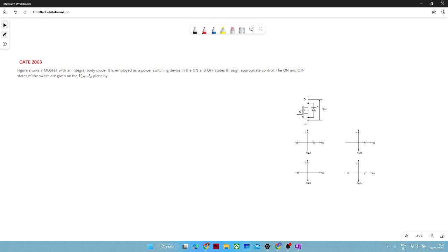It means with the help of this body diode, it can conduct, the way the diode is arranged in PN junction mode. So here we can see this is P, this is N. So in this direction, current will definitely flow, and the default direction of source current that is flowing from the drain side is indicated here.